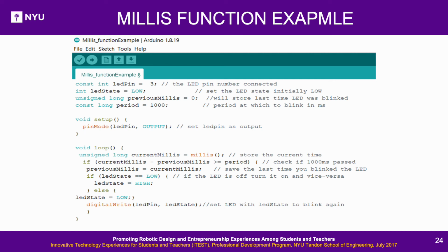Here in this example we will see how to use MILLIS function, which performs the same way as delay function. Example. Blink an LED with 1000 millisecond pause. To do this, as shown in the program, we need two more variables to keep track if the required time has passed. We have stored the current time in currentMillis variable, but we also need to know when did the timing period start, and how long is the period.